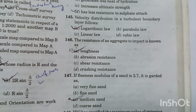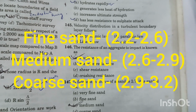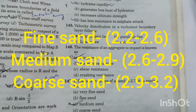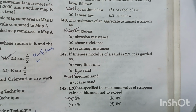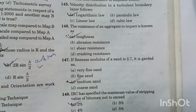The fineness modulus of a fine sand is from 2.2 to 2.6, and that of medium sand 2.6 to 2.9, and that of coarse sand from 2.9 to 3.2. Question number 148. IRC has specified the maximum value of stripping value of bitumen not to exceed 2%. Option A is right answer.